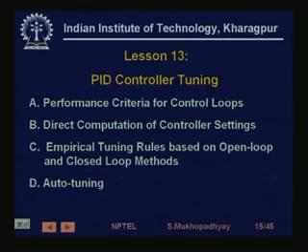and finally we took a look at auto tuning. Auto tuning is where the controller itself examines the input output signal, decides the best controller parameters for this process, and then downloads them into the controller, basically setting the PID controller parameters to those values, without human intervention. We described the method using relay control systems.